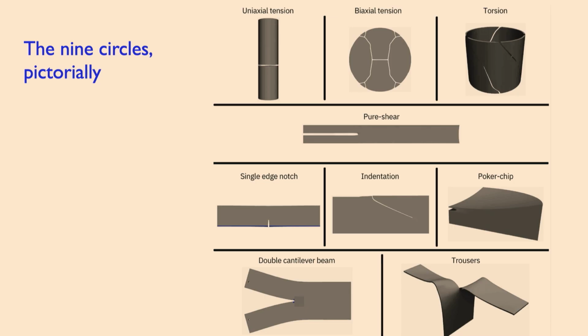And the fact of the matter is that how things get loaded can in general vary quite a bit, even within the context of the same problem, right? As the cracks evolve and stress fields change, you might be activating one part of the strength surface at one instant in time, but another just later on. And so if you don't have that representation built in, you're stuck in this spot of calibration.